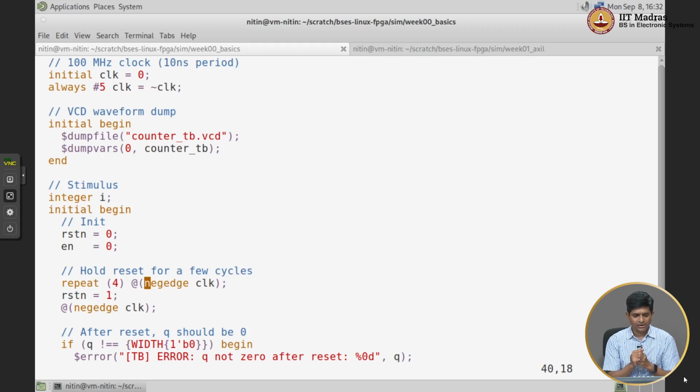By changing my transitions to be at the neg edge, I am not saying that the neg edge is better in some way. In fact, when you are building a real system, there is almost never, or rather very rarely, a good use case where you should be using pos edge as well as neg edge in your digital design.